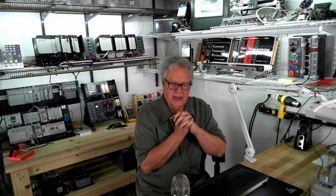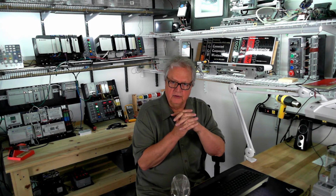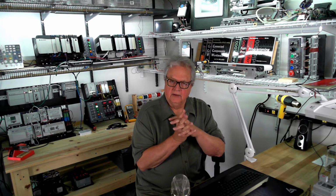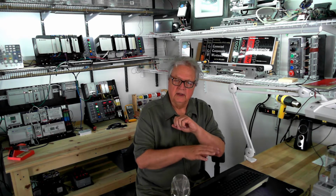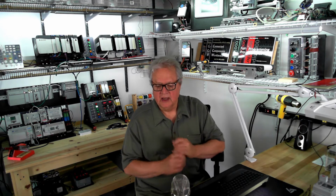Today we're doing counters. We already did timers. Timers count units of time. Counters count events, rung transitions. When a rung goes from false to true, it increments or decrements depending on the instruction. The rung condition, true-false condition, has to go false again and true again to increment or decrement one more time.